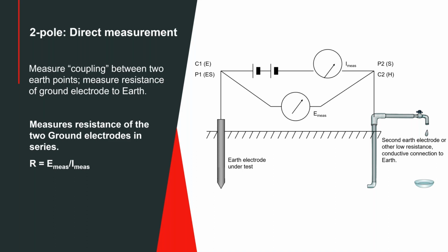Okay, you can do this. And it's basically a drop dead type of measurement for situations where you just can't do a conventional ground test, usually because you're in a very crowded environment, such as an urban environment, and you need to have something to at least give some idea of the resistance of your local ground.